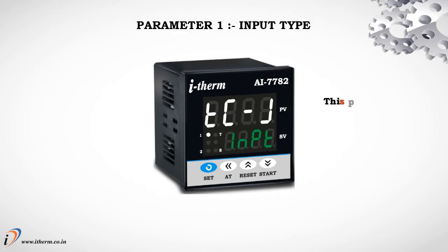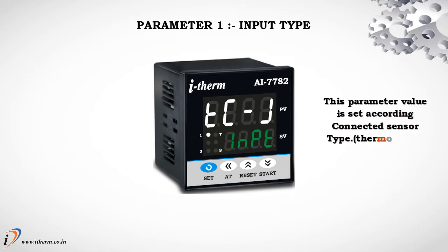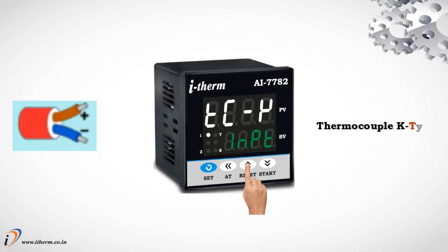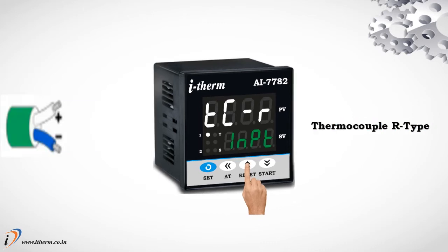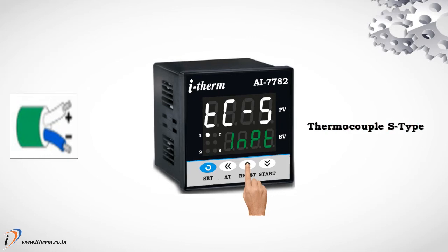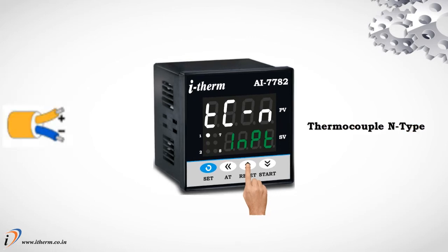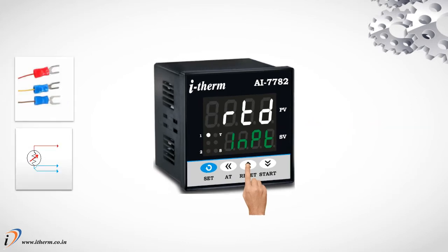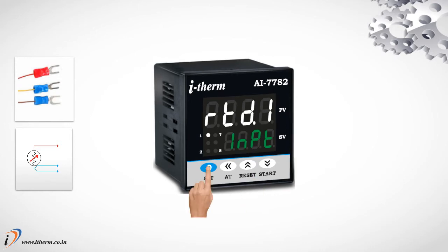Parameter 1, Input type. This parameter value is set according to the connected sensor type. Thermocouple J type. Thermocouple K type. Thermocouple R type. Thermocouple S type. Thermocouple N type. Thermocouple T type. Thermocouple B type. PT100, 1 degree centigrade resolution. PT100, 0.1 degree centigrade resolution.